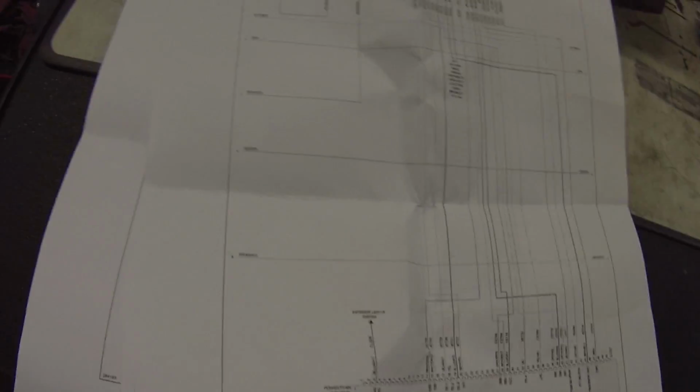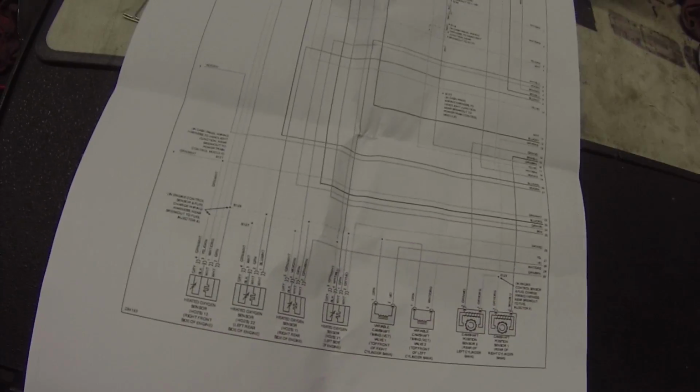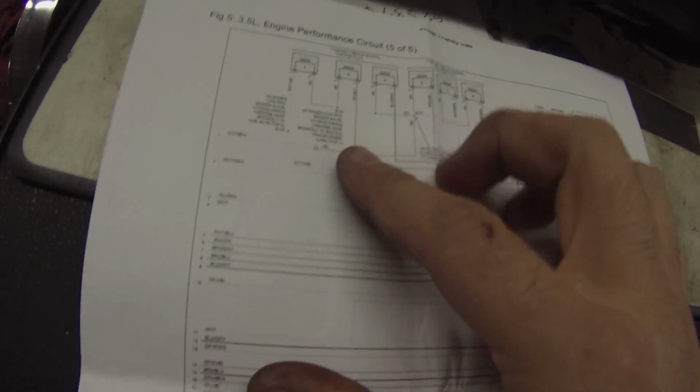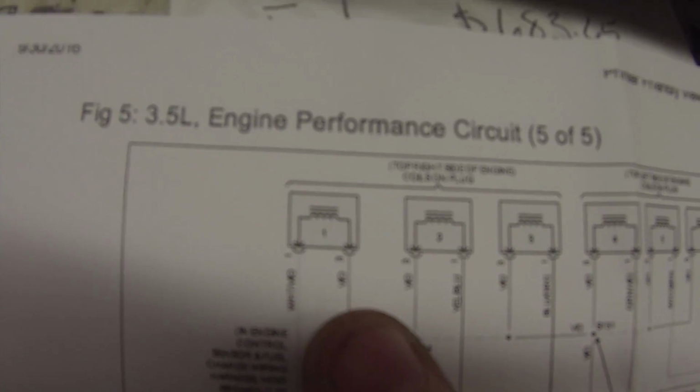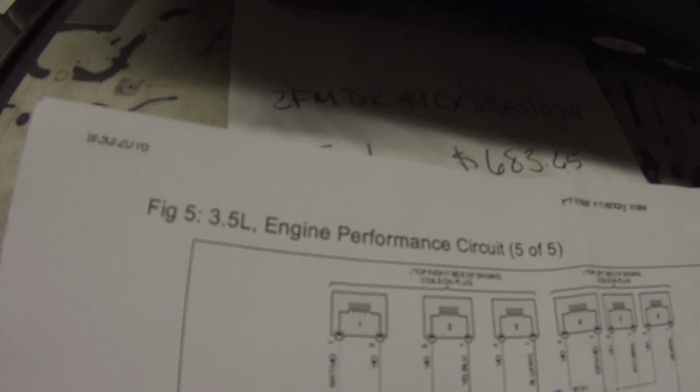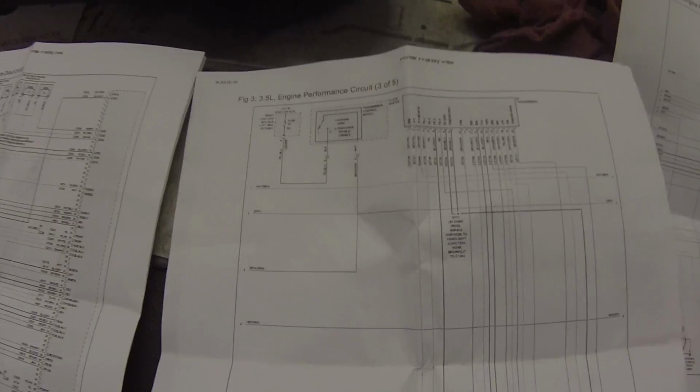Especially because of this design, I can't get to them because the intake is there. So as soon as I can find my ignition coils. Alright, so here are my ignition coils. Cylinder number 1. And they share this fuse. It is a violet wire. And that goes back. Let's see here. It's a white and brown wire, and it's going to go back all the way to the first page, and that is fuse 33.